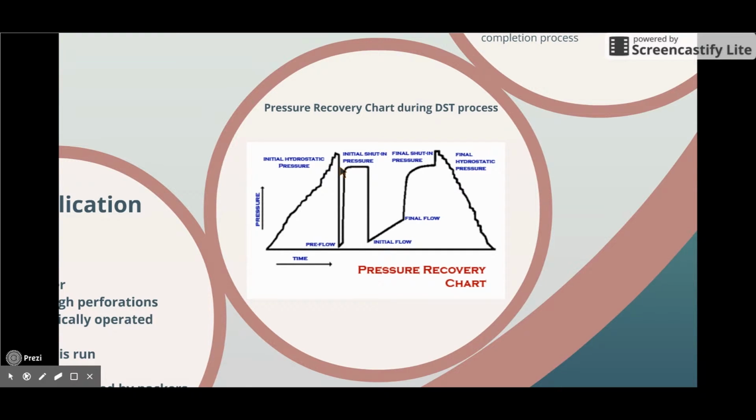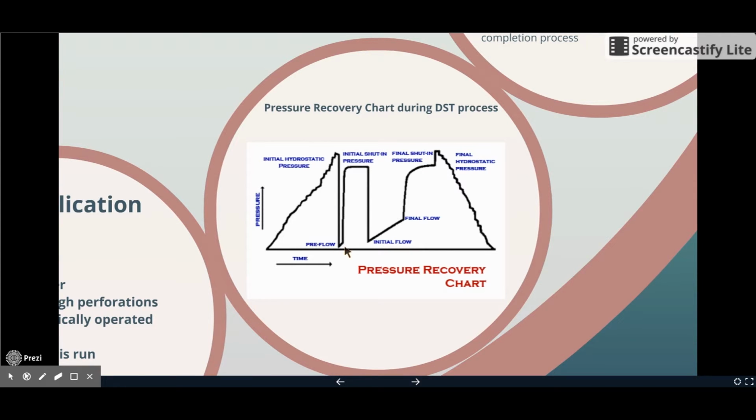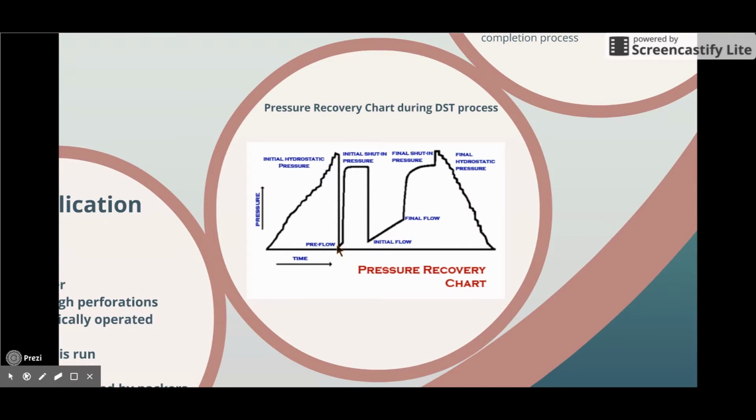The first flow period, which is also known as pre-flow. The reservoir fluid enters the test string. As the height of the column above the pressure recorder rises, it shows higher pressure. The end of flow period.